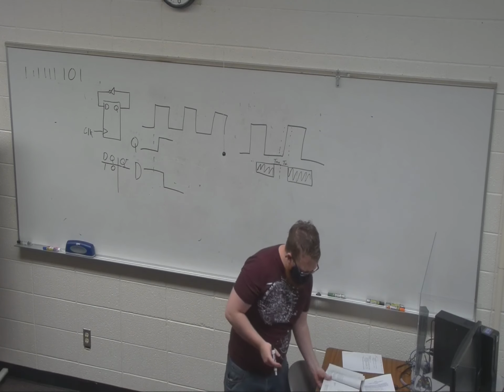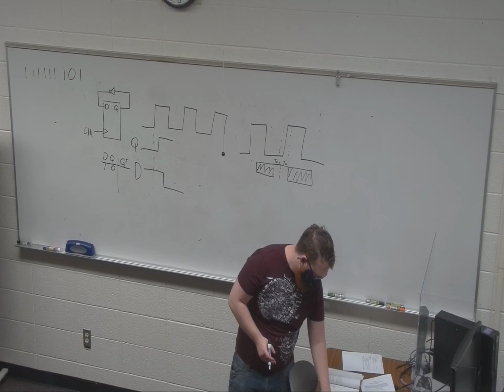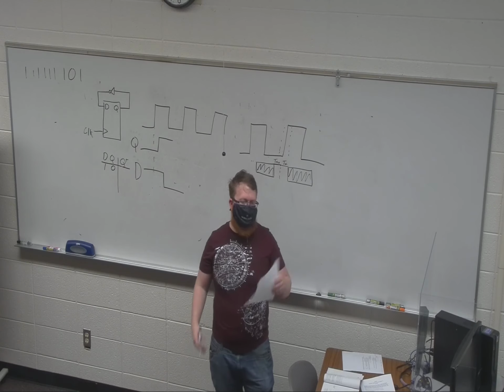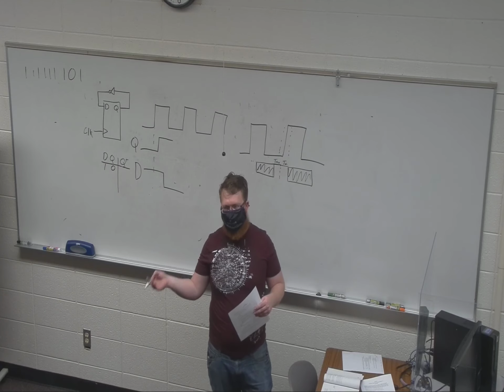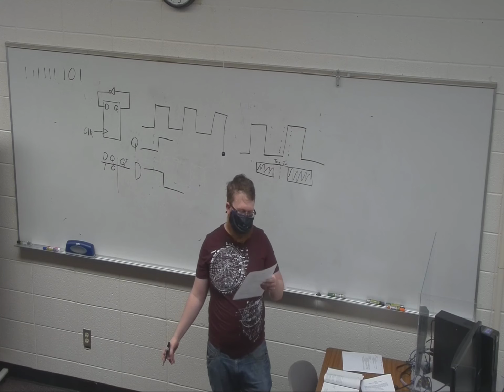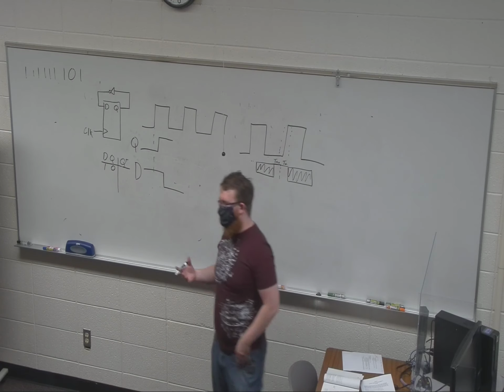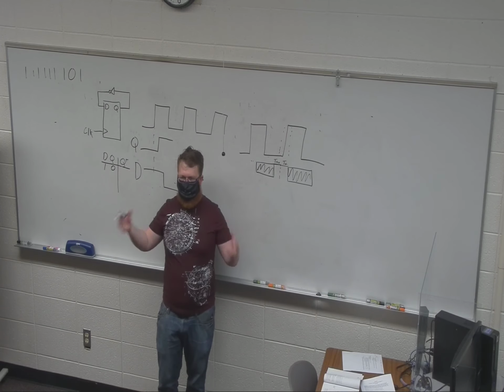So we're going to go with an example that I figured out that I think is pretty good. Let me see if I'm going to miss anything. One term that I need to make sure. If you have unequal delays in a system, a term for that is clock skew. S-K-E-W, clock skew is a term you should be aware of. And there's this assumption that happens every once in a while for students that if you have 6 flip-flops or so, they're all going to have the same delay.